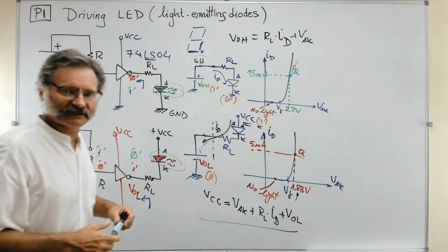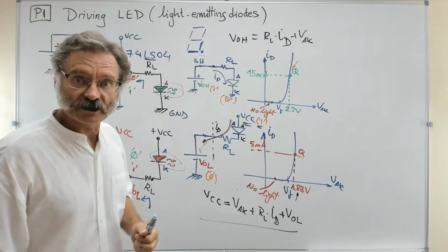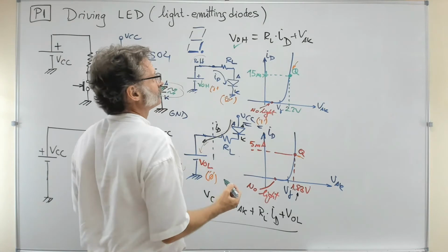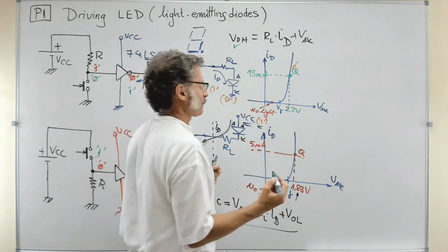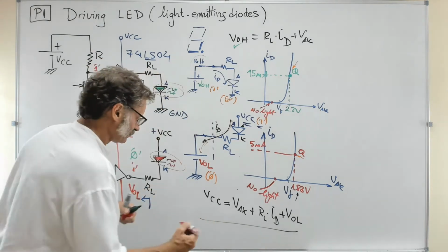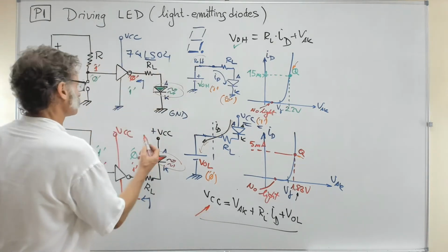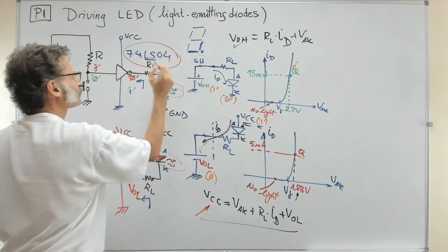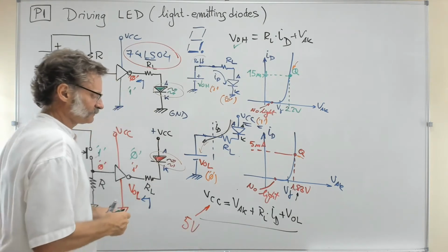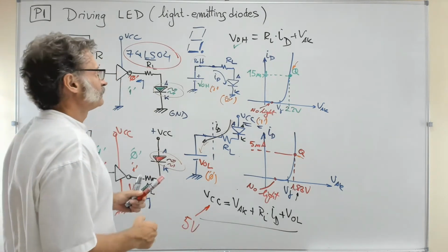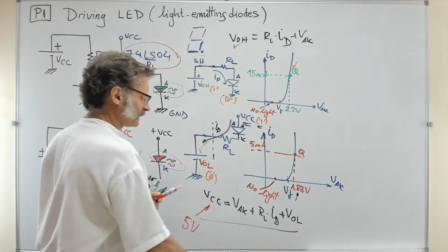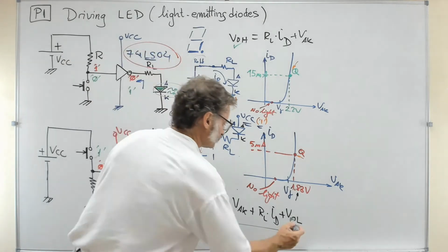So what is everything? Well, the technology is giving you this voltage from the datasheet. The VCC is, for example, 5 volts. VCC down there that you need, for example, if you are using these chips, 74LS, low power Schottky, this is usually 5 volts, typical value. VCC is given, data. VO high is given as the same because it came from the datasheet, like this one here.